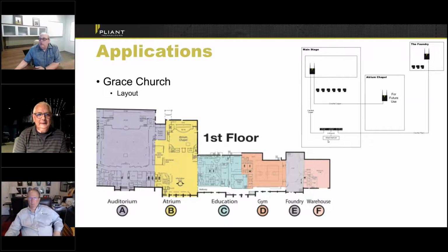I was just going to mention, I do remember distinctly when I did the demo, I came out there and I put down my control unit and we plugged an XLR cable into the 2-wire interface. Yep. And we have a function on our system, which you can either run from TrueWare or from the control unit itself, called auto null. And that takes into account all the cable resistance, inductance, capacitance, and basically cancels out any noises or echoes in the system.